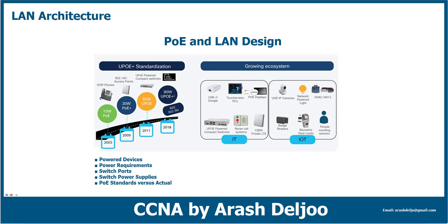About PoE, you can consider these factors. The first is the powered device. You need to determine the type of devices that you are using in your network, the models of those devices, and also the power requirement of those devices. This is so important for choosing the switch model.